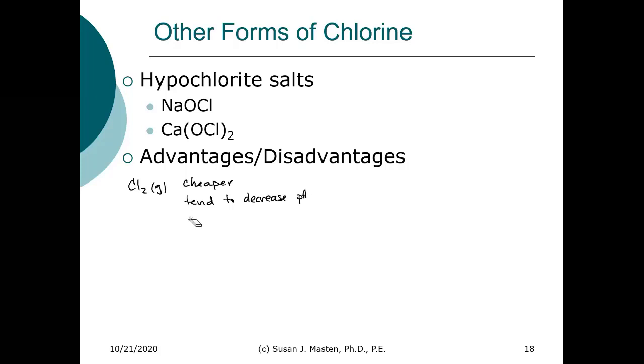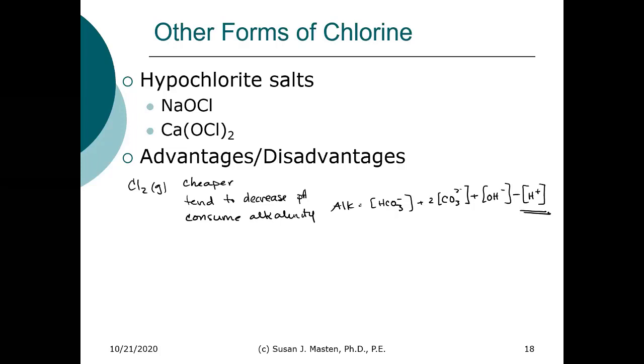It will consume alkalinity. If you remember, alkalinity is equal to bicarbonate plus 2 times carbonate plus OH- minus H+. So if we increase H+, we lower the alkalinity.